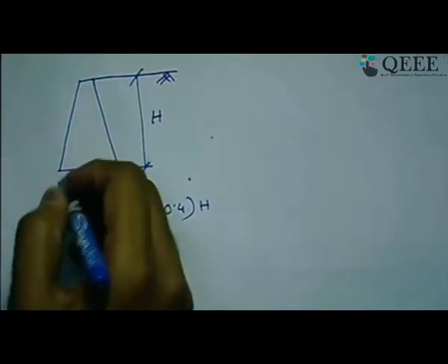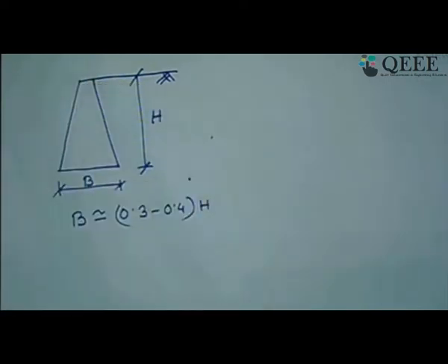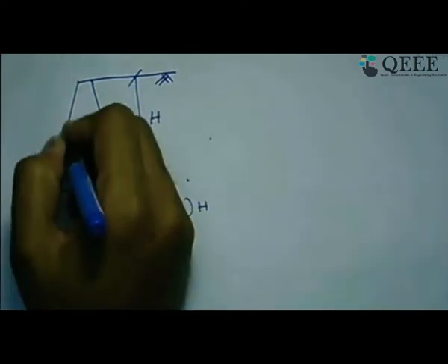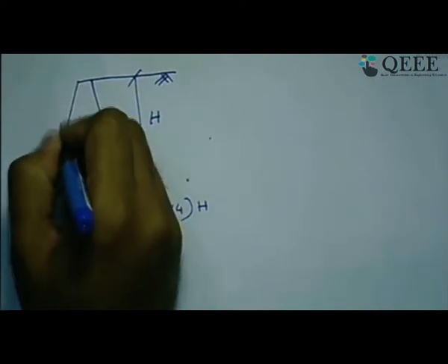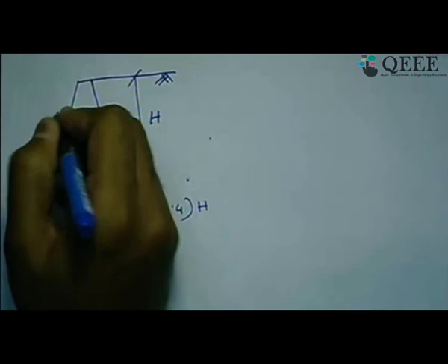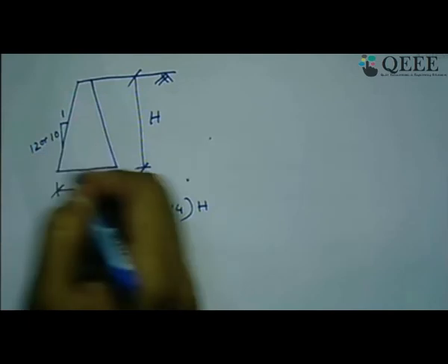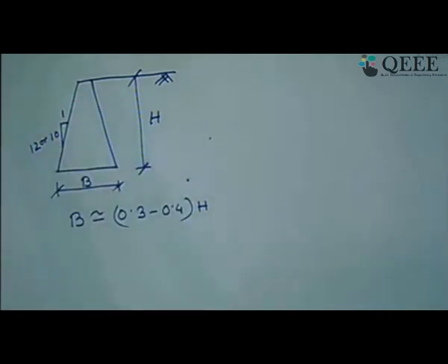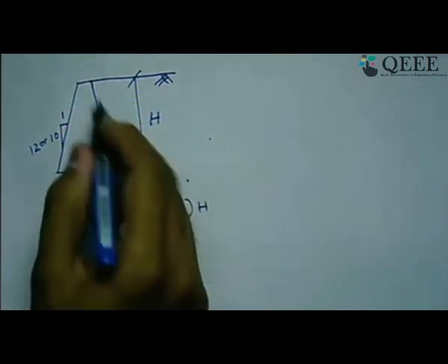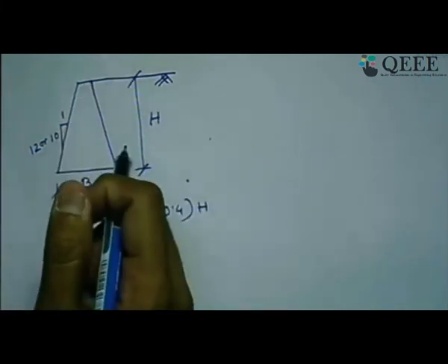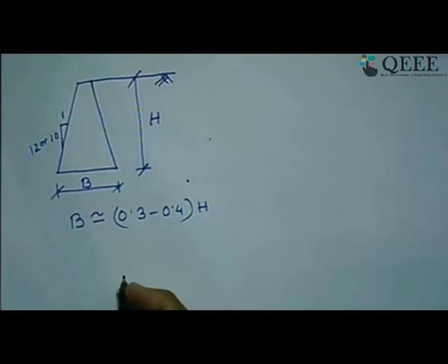And now what angle should you use here? There are different possibilities. The slope angle is typically considered as either 1 in 10 or 1 in 12. So these are the typical angles by which the taper of the retaining wall is chosen. And how much weight of the wall you have to provide for stability, that we should cover in the design of the gravity retaining wall.